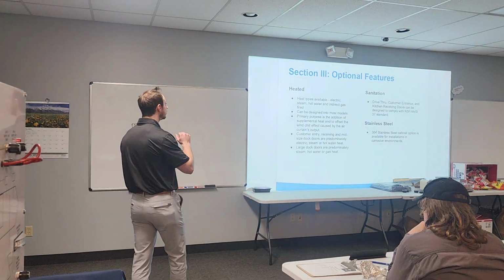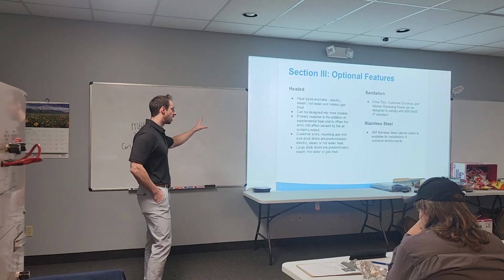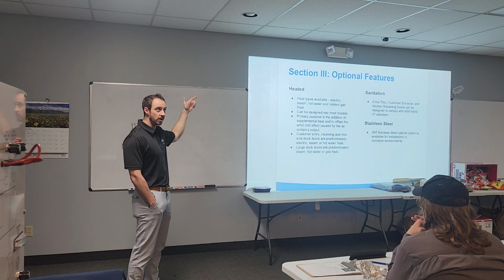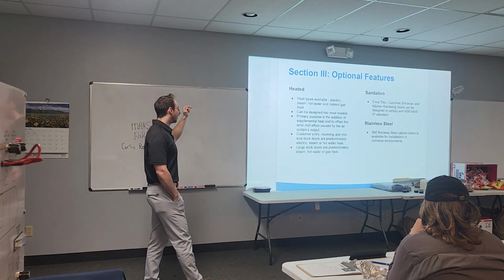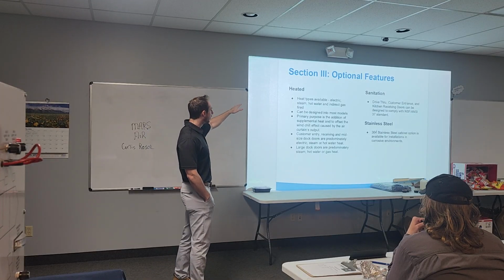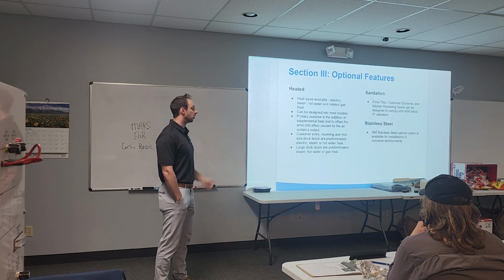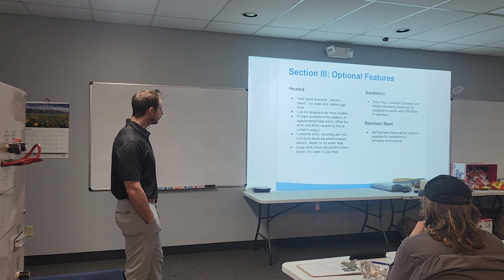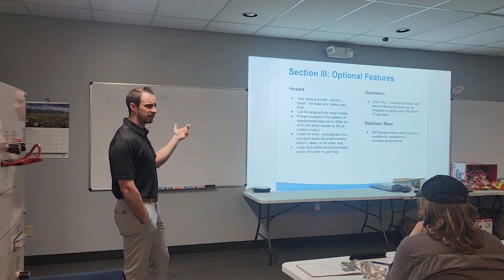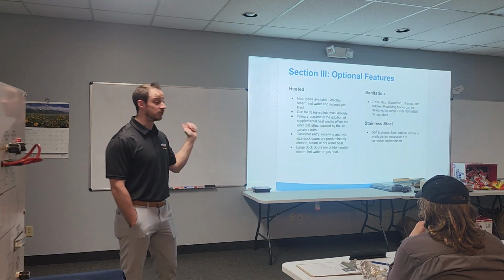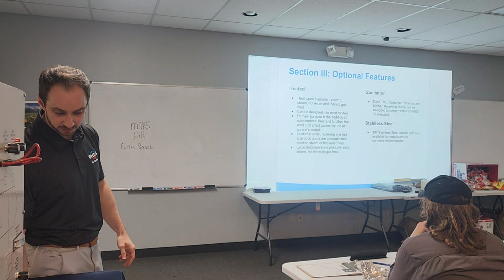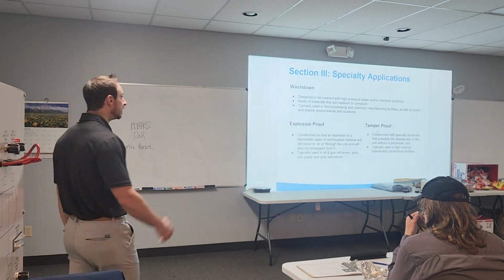Couple options. Typical options we have, not all of these, are kind of highlighting the main ones. We do have heat options, so I'm sure you guys would probably want that out here. Electric's probably most common, but we do steam, hot water. Our larger industrial units, we could do indirect gas fired heat as well. Sanitation, you guys probably don't deal with NSF, that's more of a food service thing. But we do have 304 stainless as an option. We can do 316 too, if that's something that you or your customer would need.